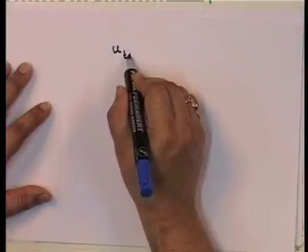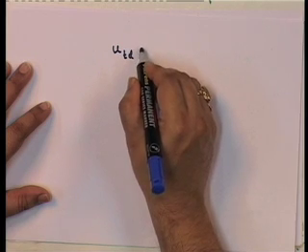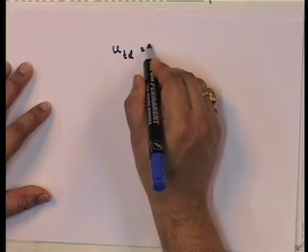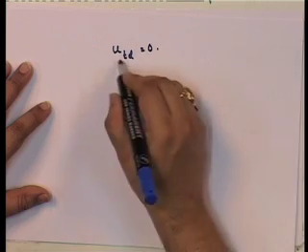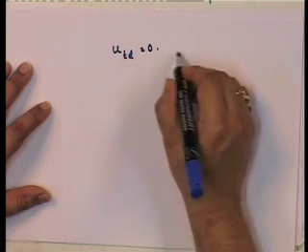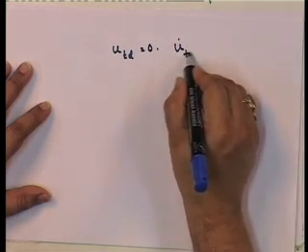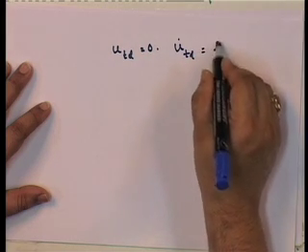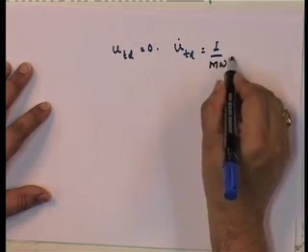If I now extend this to a damped system, let us look at this. We did see that you had a situation where u of T d is equal to 0, T d being the end of the impulse, and u dot T d is equal to I upon m omega.